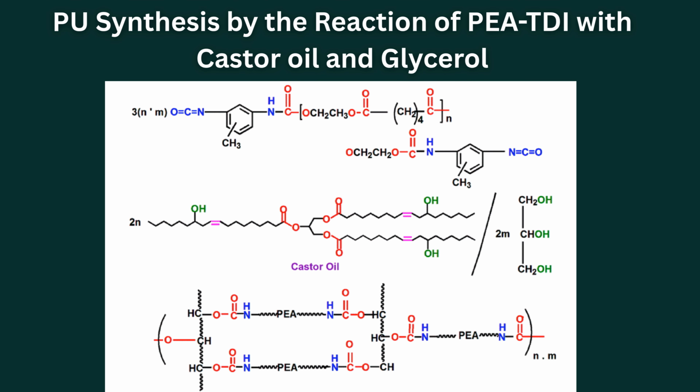In another approach, amorphous polyurethanes prepared via transesterification of castor oil demonstrate low glass transition temperatures and good thermal stability, making them suitable for polymer electrolyte applications. Their flexibility facilitates ion transport, enabling measurable ionic conductivity when doped with lithium salts.